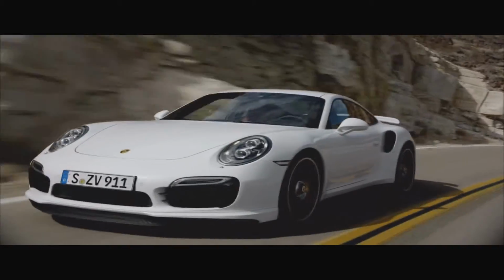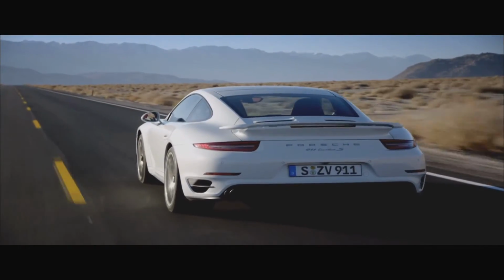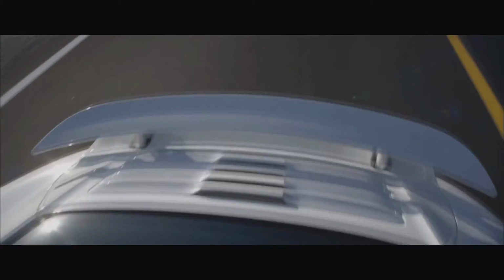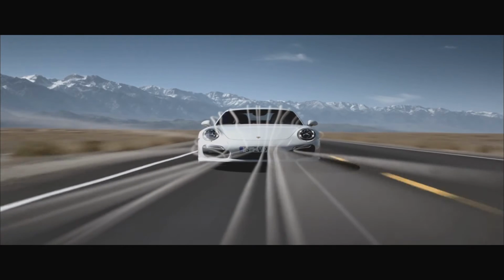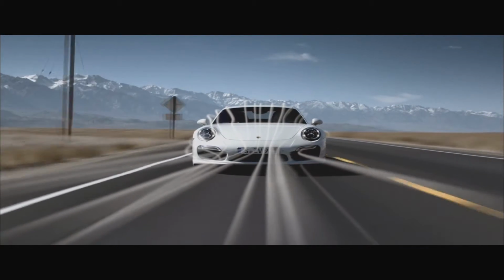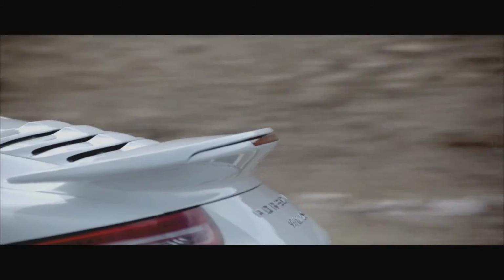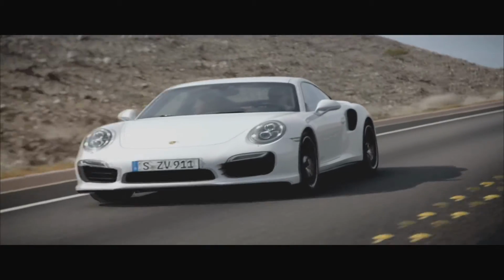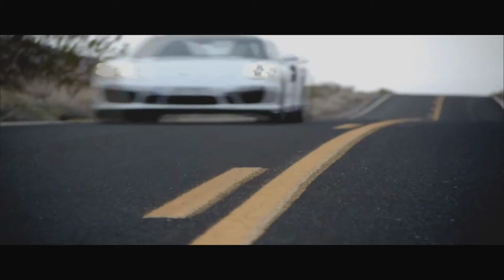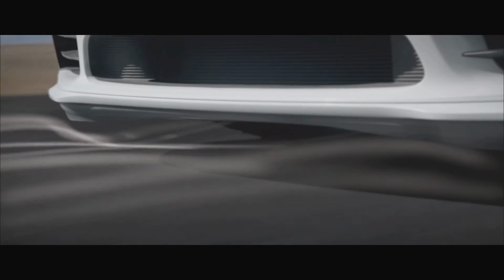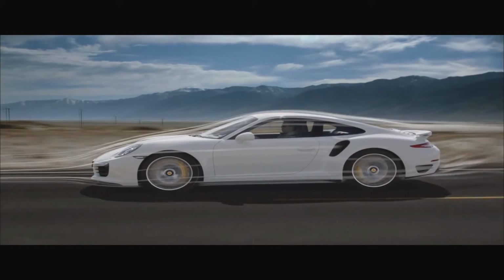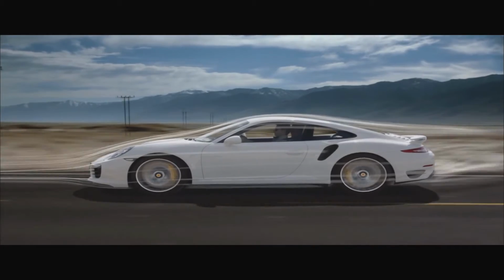The active front spoiler lip and the rear wing can be retracted and extended in 3 stages. Stage 1. Start. Both spoilers are completely retracted. The greater road clearance at the front improves suitability for everyday driving. Stage 2. Speed. From 120 kilometers per hour, the front spoiler and rear wing are partially extended. Agility and driving stability increase. Fuel consumption remains low, and the maximum top speed can be reached.